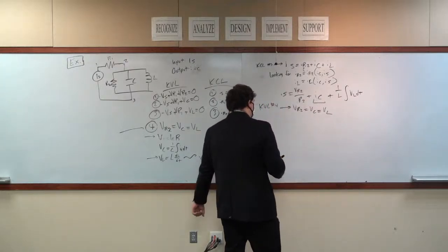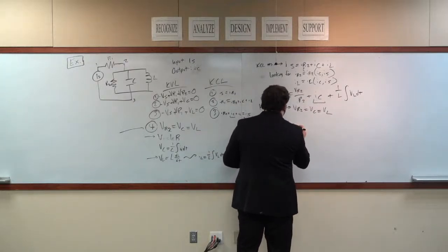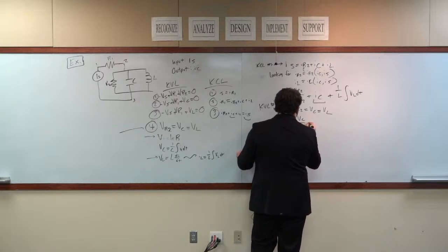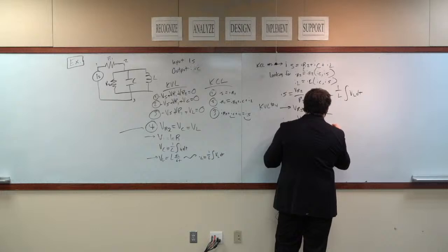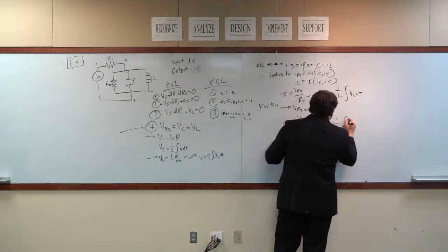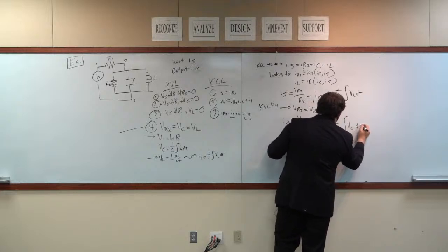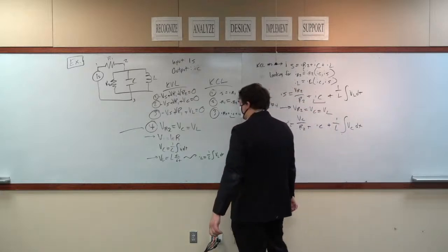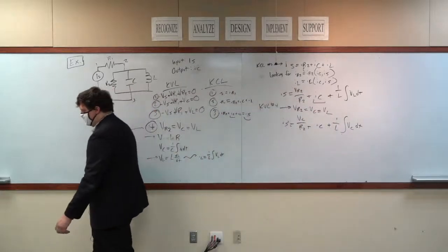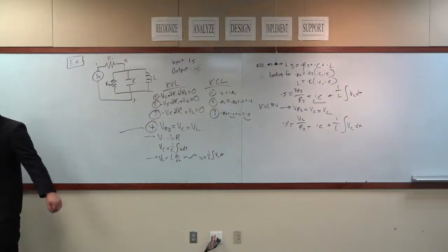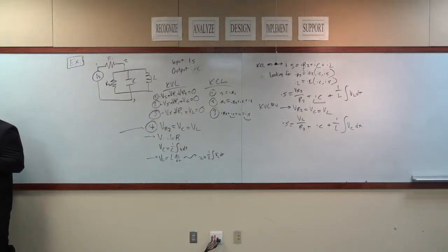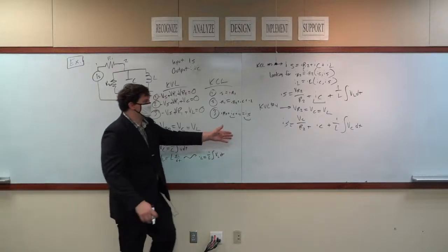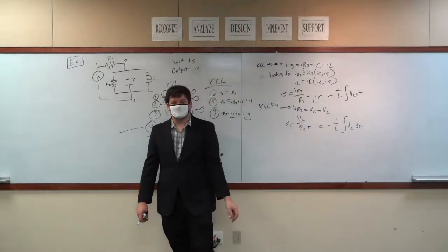That's good. So now if we plug that in, IS equals VC over R2 plus IC, which is already there, plus 1 over L times the integral of VC dt. Now this is about to get super ugly. We now have everything in terms of the voltage across the capacitor, except for IC, which we could change into this.